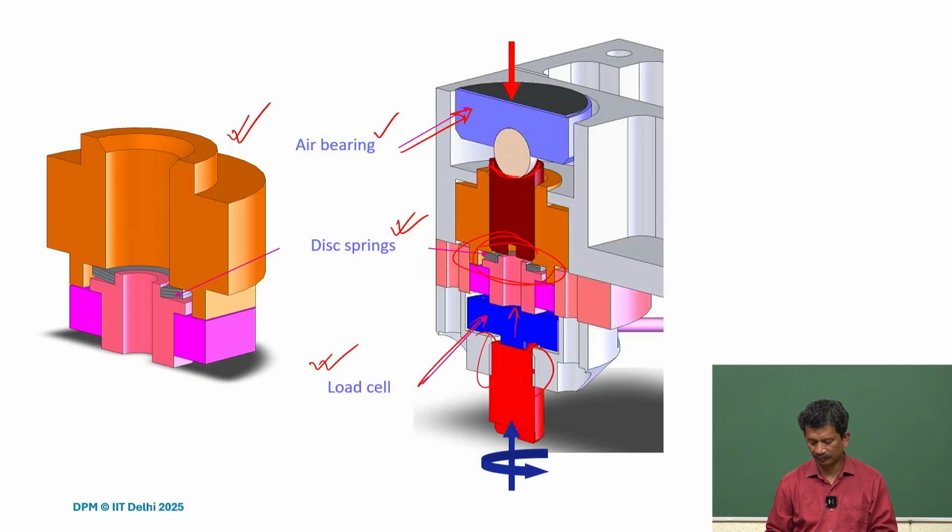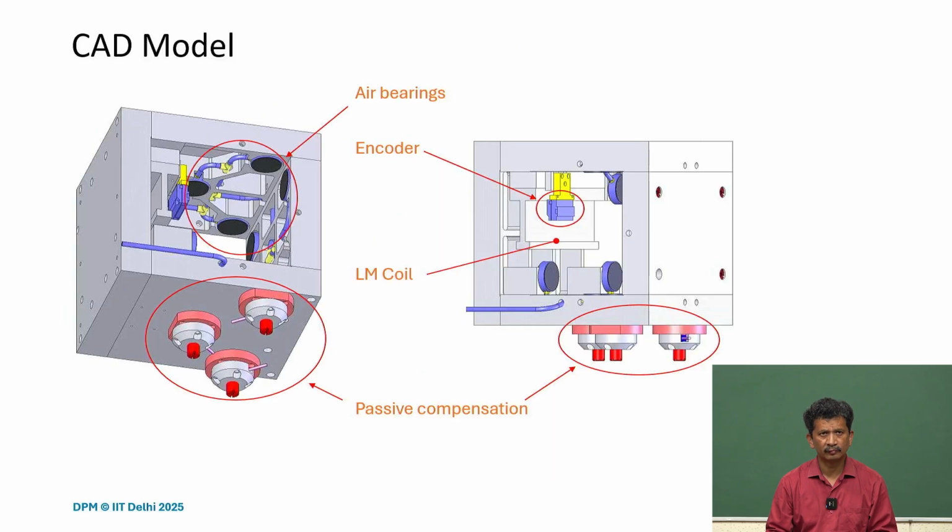So that was the idea, and this is how it's designed. All aluminum, so a lighter material, and of course we have to also look at the stiffness, because all are preloaded. It is applying forces in the perpendicular direction, all outward. So it will bulge, and if it's an open construction, the stiffness will be very low. So from a stiffness point of view, we have to also look at the design. We cannot have a very thin structure, otherwise it will bulge out.